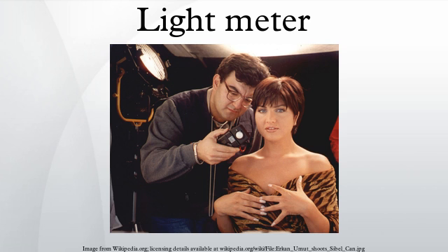There are, however, significant obstacles to overcome in order to achieve a successful implementation of light meters in lighting systems, of which user acceptance is by far the most formidable. Unexpected or too frequent switching and too bright or too dark rooms are very annoying and disturbing for users of the rooms. Therefore, different switching algorithms have been developed. Difference algorithm: lights are switched on at a lower light level than they switch off, thus ensuring the difference between the light level of the on state and off state is not too big. Time delay algorithms: a certain amount of time must pass since the last switch, and a certain amount of time at a sufficient illumination level must pass.